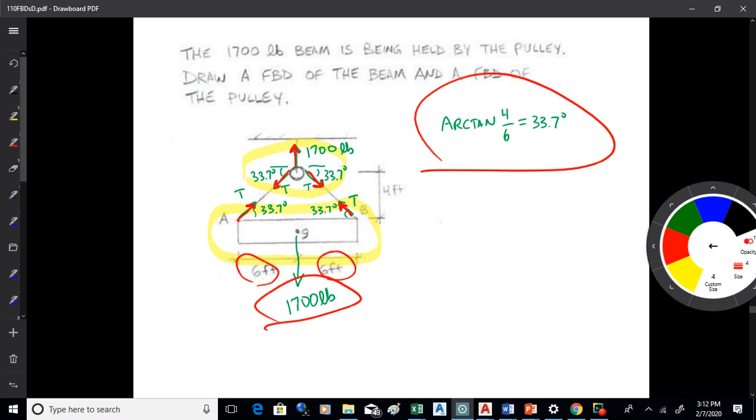I have a question. Since the tension is the same across the pulley and the weight, all tensions are the same. Right, in those angled cables, you're right. All those tensions would be the same. That's why I put one variable on them. The variable is T. Everyone's marked T, so I can solve once for T, and I've got it for every one of them.